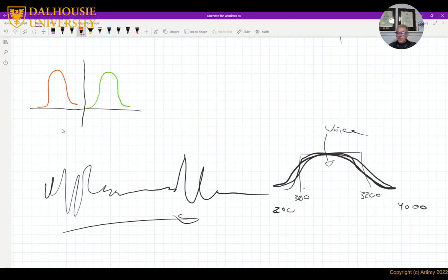What does it mean? Does it mean there are negative frequencies? No, there are no negative frequencies. It's just that when we analyze the signal with Fourier transform or other techniques that convert the time domain signal to the frequency domain, mathematically there must be positive and negative sides, right?